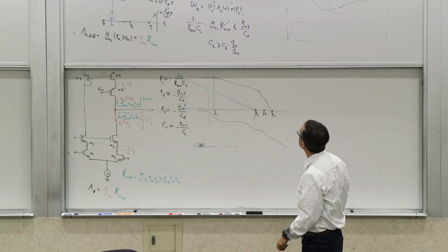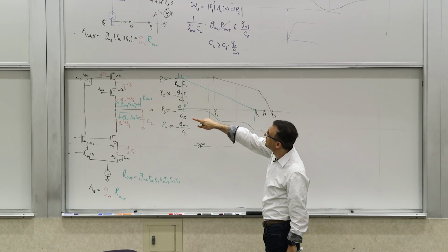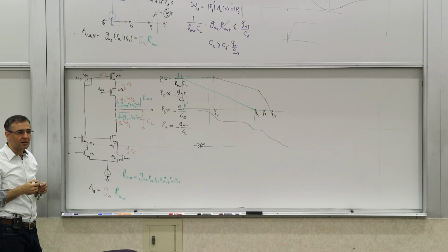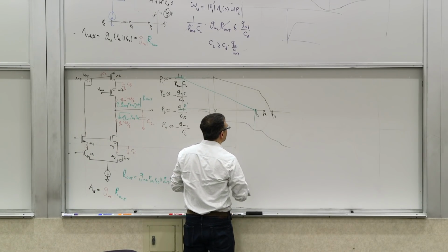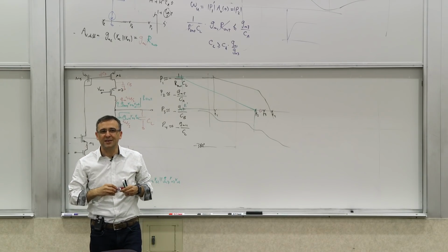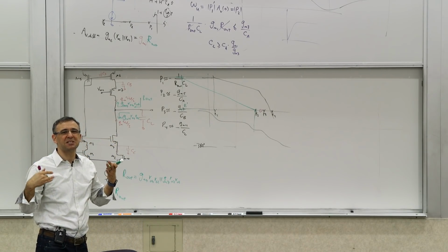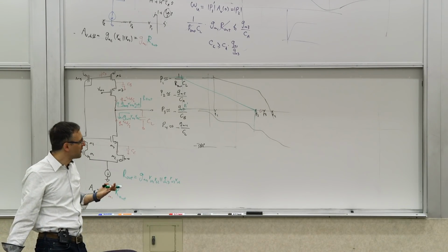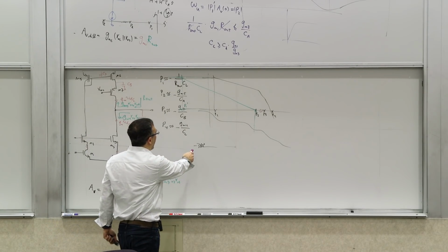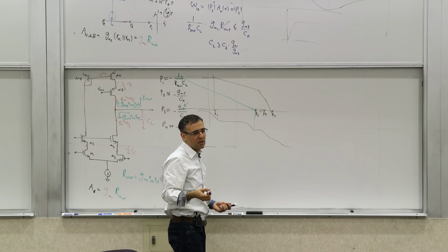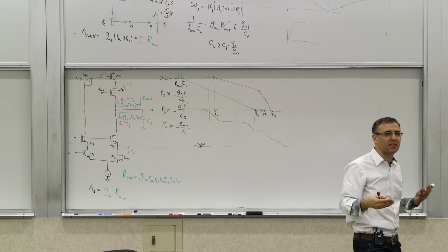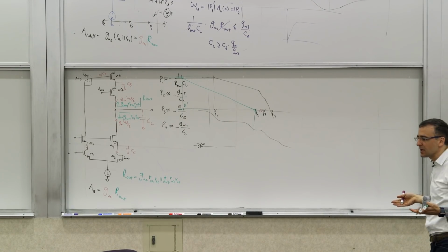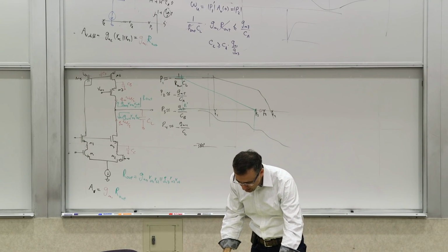There is a little bit of a fly in the ointment in both of them, which is that zero that's introduced because of this dual path, right? So you have that zero, and that zero roughly sits here, approximately. I mean, it could be back and forth. So that zero pretty much to first order cancels the effect of one of those poles, which is an okay thing, because it's a left half plane pole. So it's not as bad as this, but it still allows it. So the process beyond this becomes a little bit of an iterative process. You shoot for something first-hand, then you evaluate it, assess it, and see where it is. And you see if, okay, I need more phase margin, less phase margin, things of that sort.